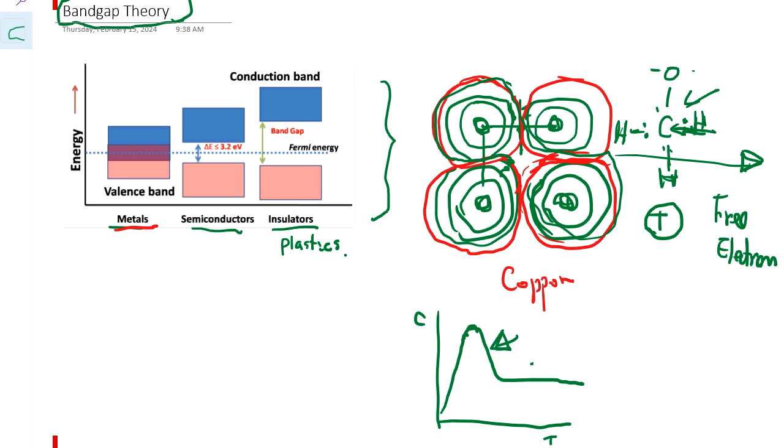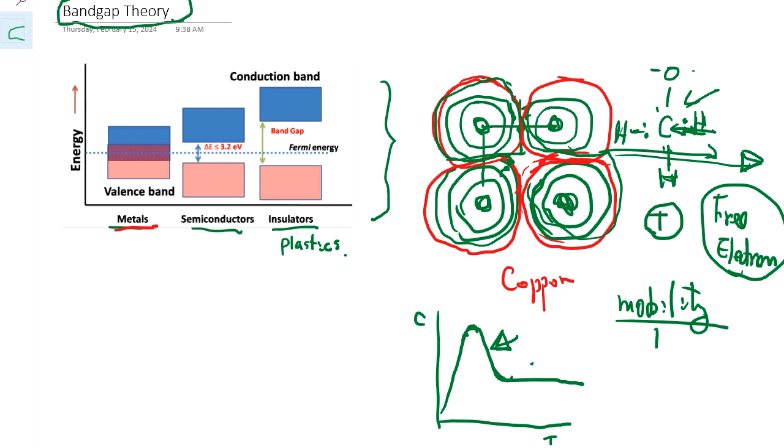But beyond a certain temperature, it goes down. Why that? Well, it generates a lot of free electron and conductivity increase, but mobility decrease, because when atoms start vibrating much harder by temperature, then electron is not easy to move around because it acts as a resistance. So mobility is related to resistivity. Okay, so there are several factors for conductivity.